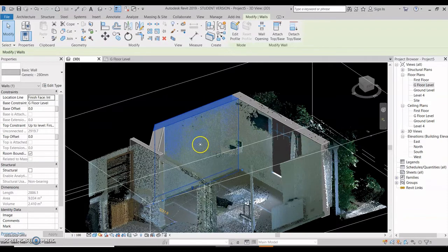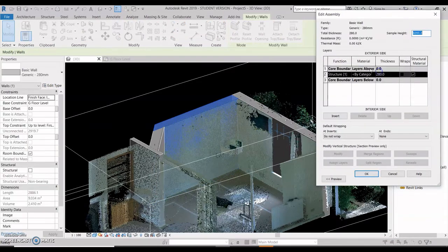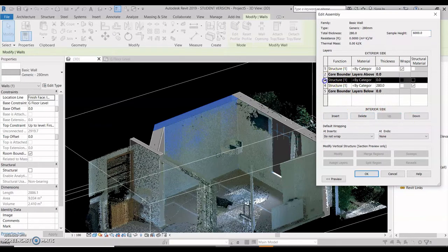specific type of wall. So how do we edit the wall for LOD 300? You can simply select the wall, go to edit type, go to edit structure. Here you can create layers. I will be creating 2 layers to show you all quickly. So up, 1 layer down.